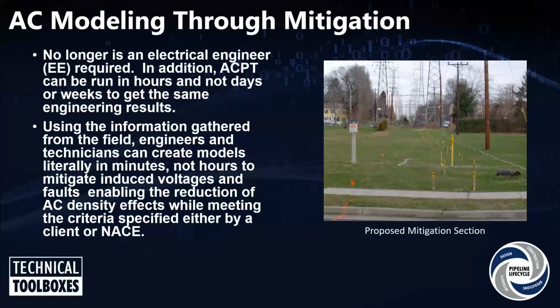So anyway, the key to this is, yes, the program will do 3 types of mitigation. It'll do discrete, like a deep well, distributed, multiple vertical anodes or horizontal anodes, and or parallel anodes or cables, whether you're using copper, zinc, or a material of your choice. So this is what makes it nice. And we do follow the NACE criteria and things of this nature.